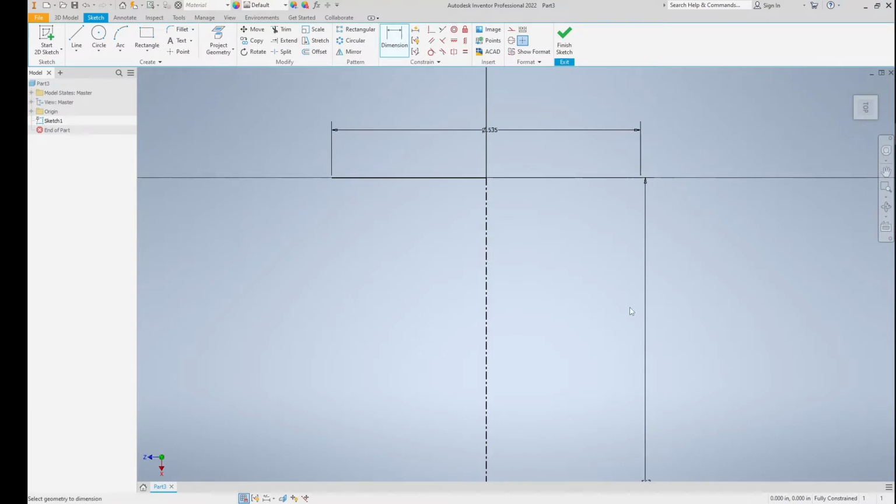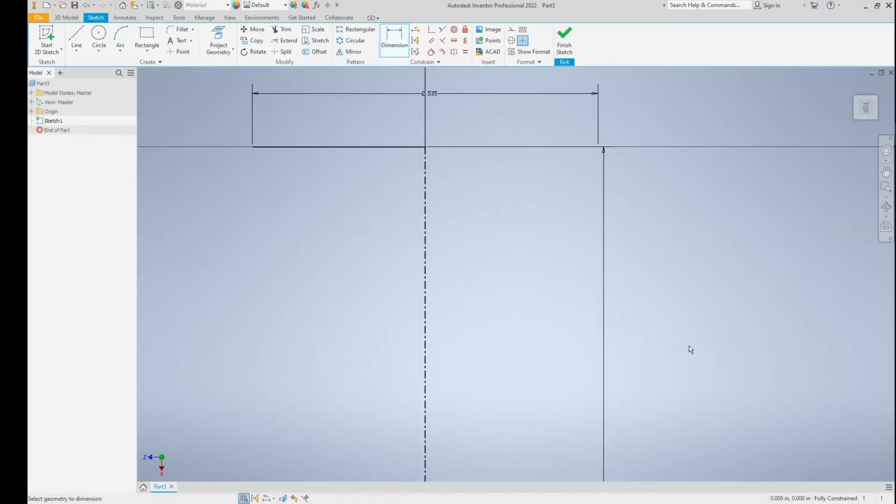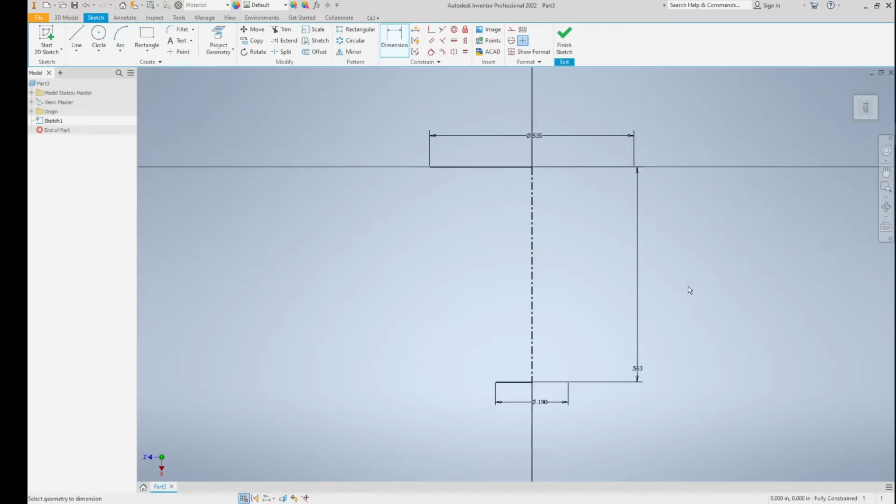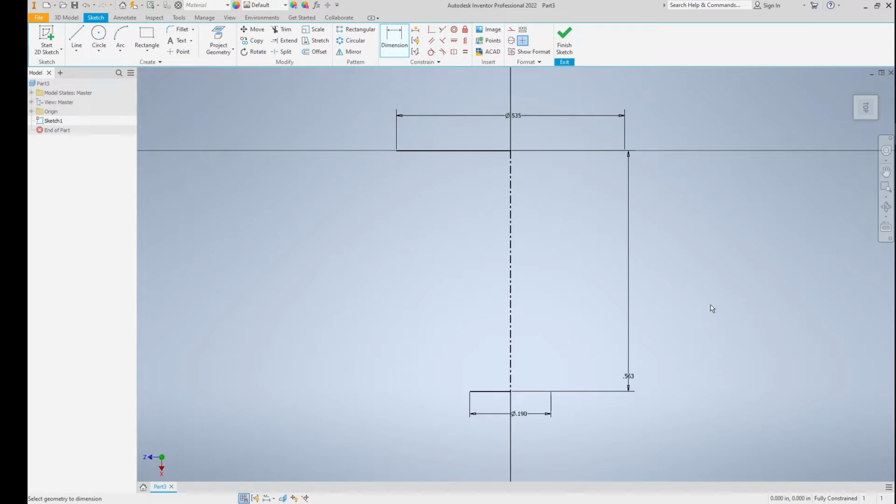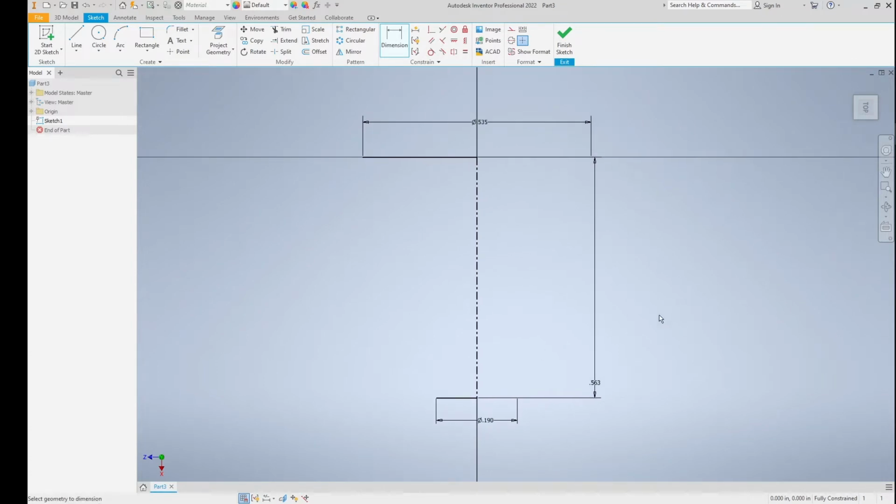Okay, I'm going to zoom out. There we go, that's a little better. Now I'm going to create a 3-point arc, which is this one. I'm going to select this end point here and then this end point here. And again, in the size, you're going to type in the box 1.5. That should be the radius. Enter. Now we can finish the sketch.